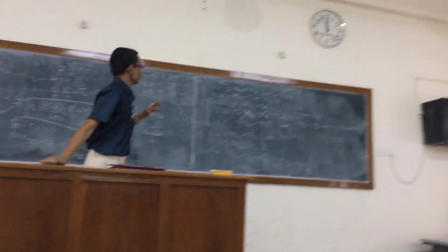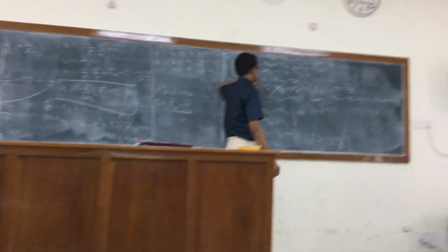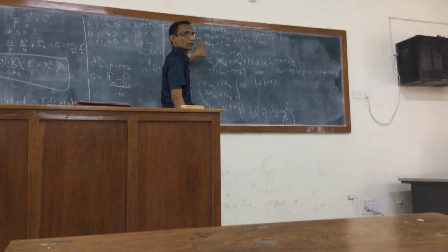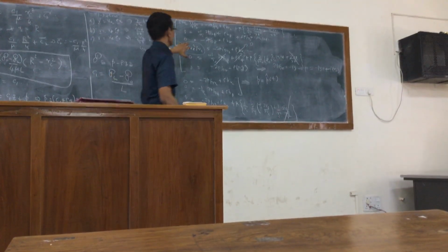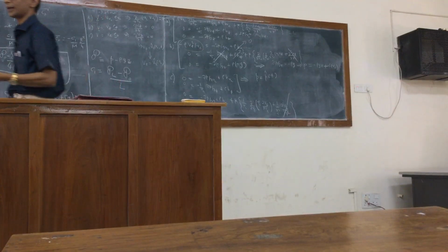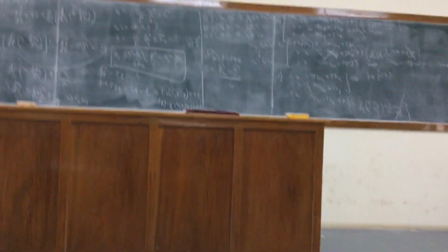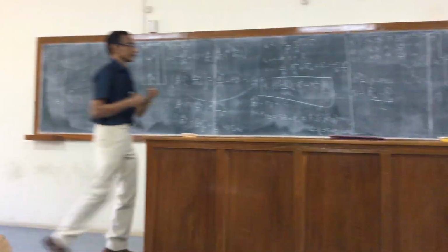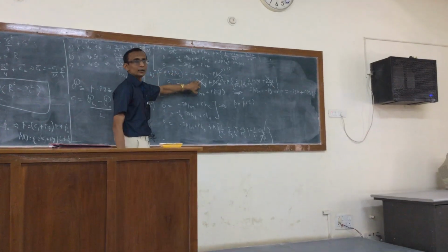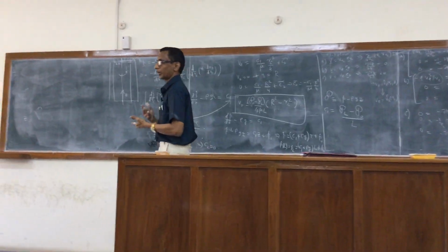So the argument Lightfoot gives is that the pressure variation in the Rc direction is given by the centrifugal or centripetal acceleration, and the dependence of the pressure on Z is provided by gravity, whereas here it is provided by the rotational motion. Whereas there is no reason to expect anything driving the pressure gradient in the phi direction.